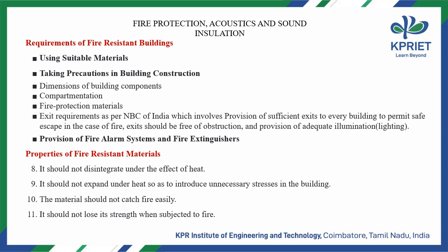Properties of fire-resistant materials. It should not disintegrate under the effect of heat. It should not expand under heat so as to introduce unnecessary stresses in the building. The material should not catch fire easily. It should not lose its strength when subjected to fire.